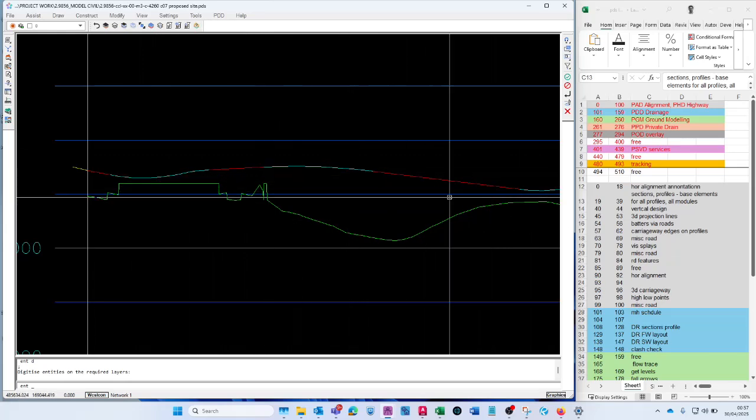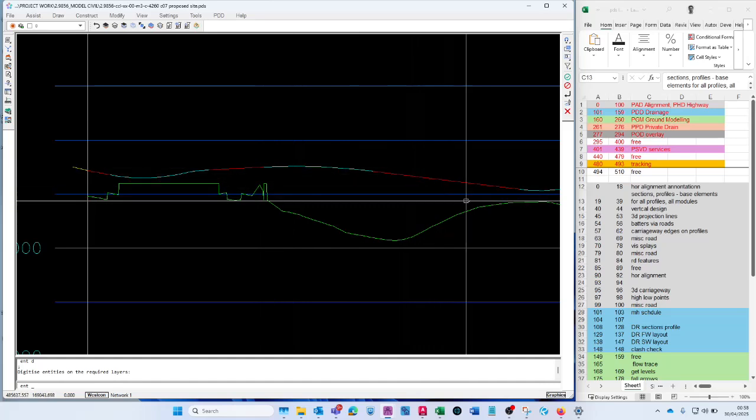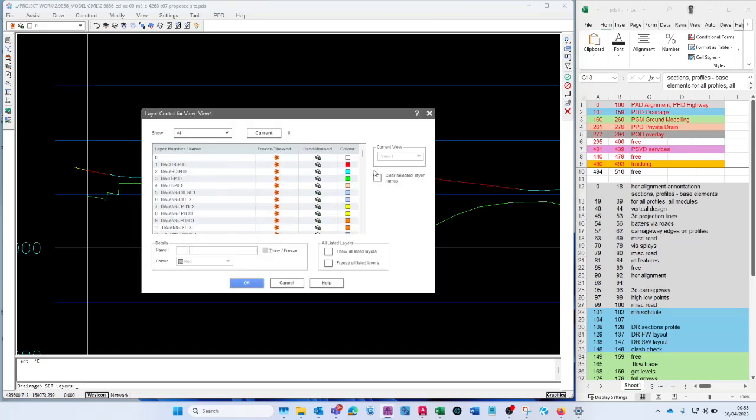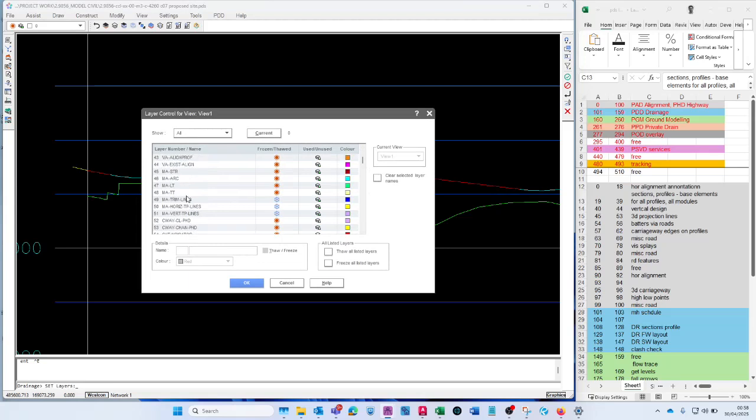And if you did the highway alignment design, you'd have a few more extra lines in this just for that. Let's scroll down. So vertical grade parallel, which is what those two are. Crossfall alignment, existing alignment. These ones get used when you're doing the PhD highway. So if you can't see your road vertical design, it'll still be this group that's turned off.